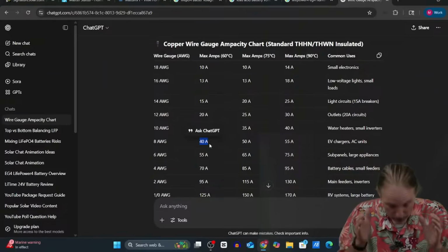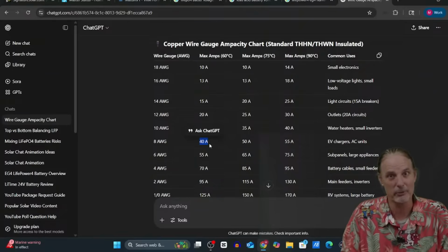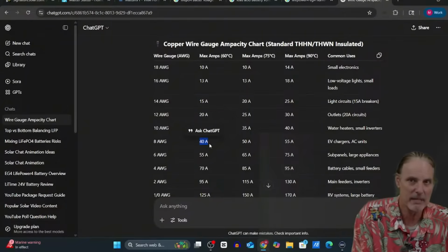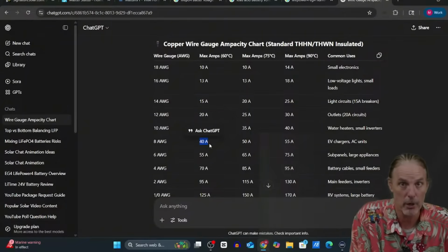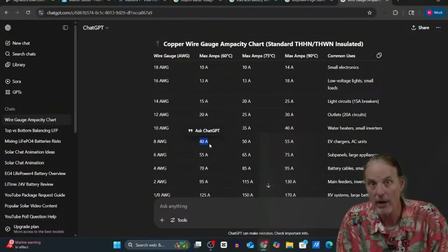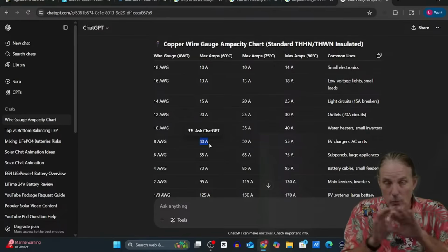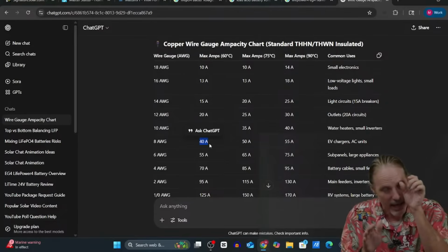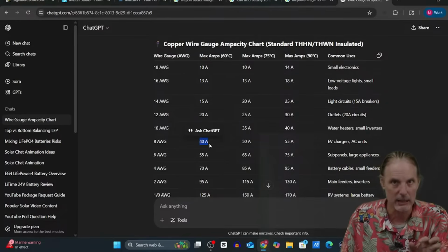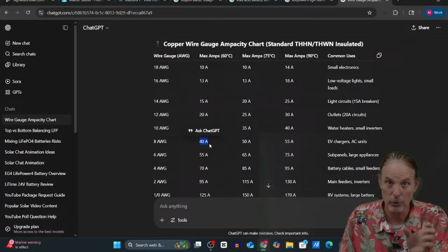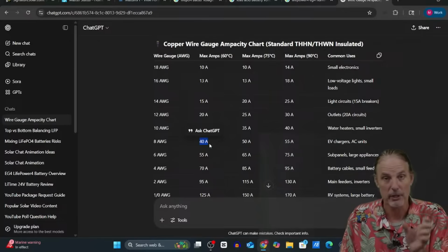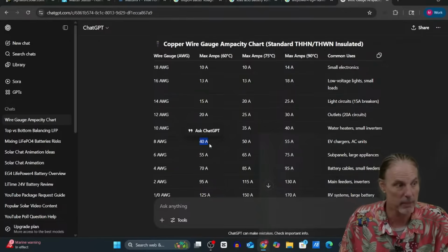And this is where one of the most common mistakes is, people don't take this into account. Yes, the BMS can support 100 amps or 200 amps, but can the wire of the system, can the bus bars of the system? You want to go through all of your equipment and make sure that the weakest link is what you're putting that fuse on, because that's where you're going to run into the biggest problem.